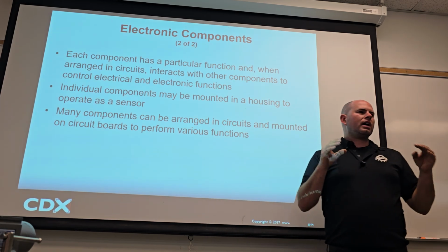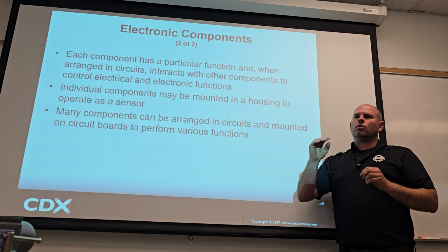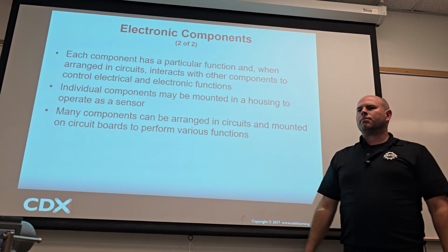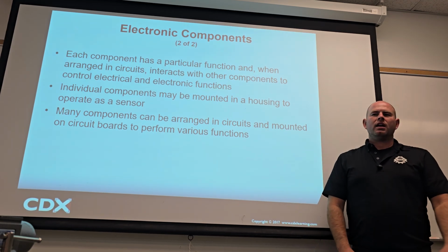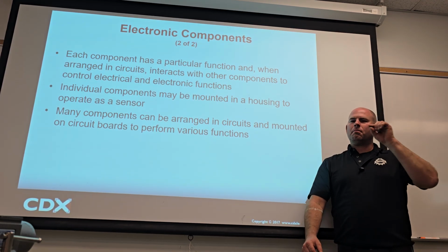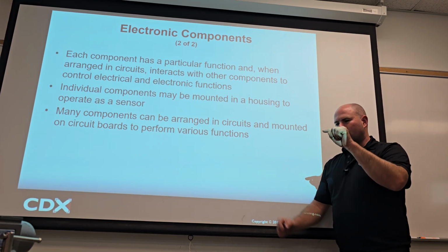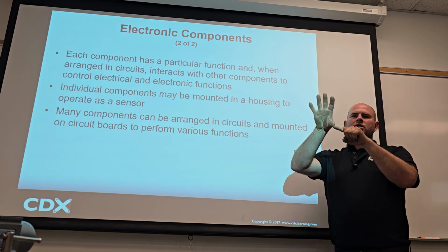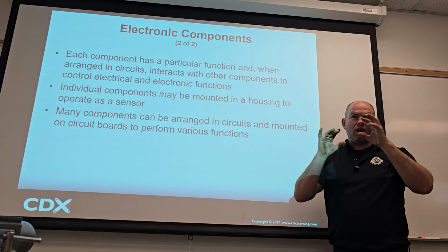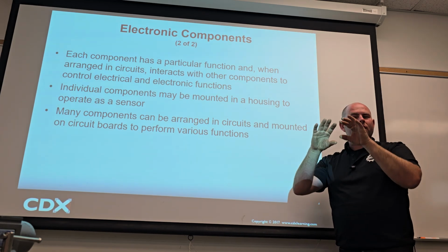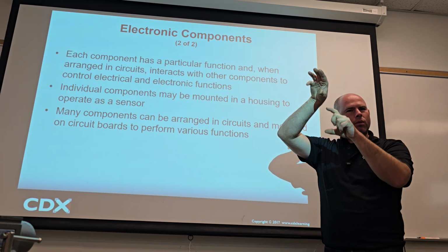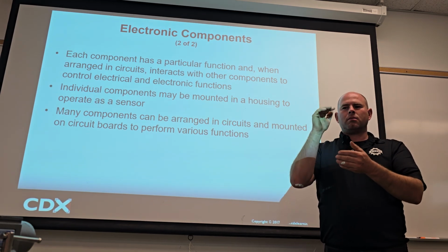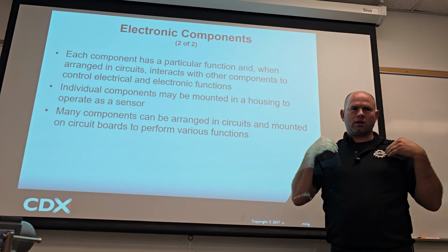Now, as you go about your diagnosis and try to understand it, you don't say, oh, this computer must be fried or this computer must be shot, because that's kind of a guess. You want to measure and say, I should get 12 volts here. I'm not getting 12 volts here. And I know that in the ECU, this is controlled by a transistor. I know the transistor is bad, but I don't really care exactly about whether it's the transistor or the little printed circuit board or whatever. But you're like, yeah, I've got really good evidence for why this ECU is bad because I'm not getting 12 volts here. Cool. That's how we diagnose stuff.